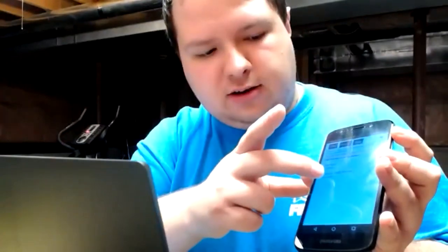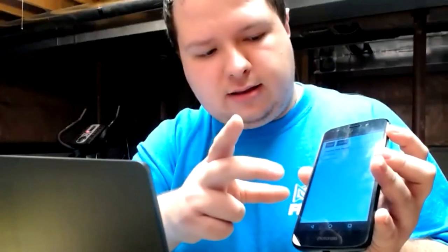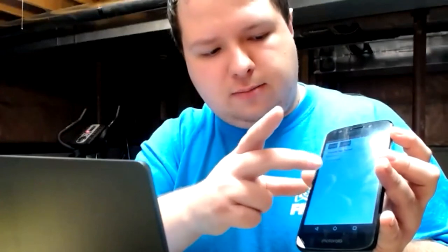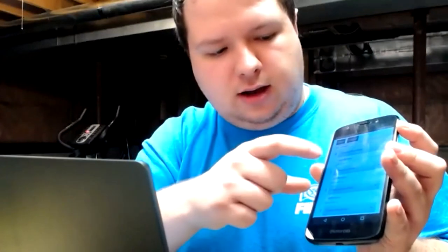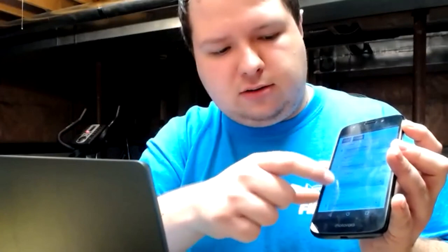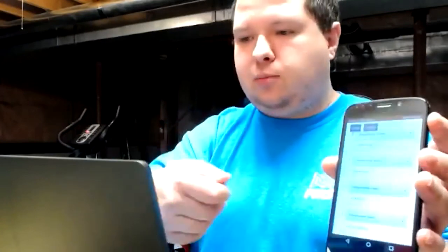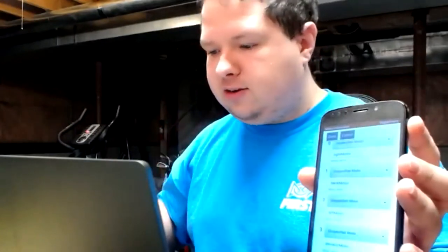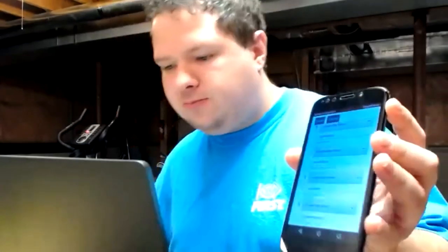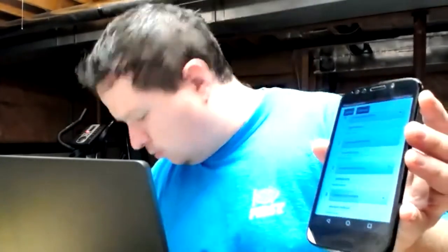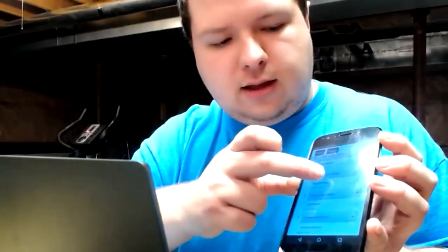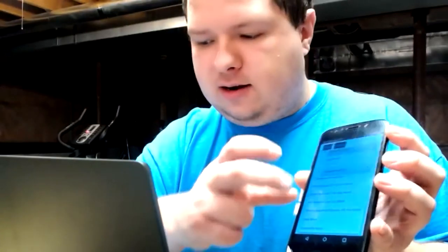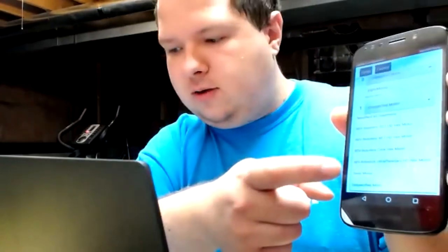You'll then find the Control Hub portal. Click on that. Click on the Control Hub. Then you want to click on Motors. And you'll see there's motor ports 0, 1, 2, 3. So depending on which port you plug your Tornado into on the Control Hub. So for example, if I plugged into port 1, I'd look at port 1. I'd click on the drop-down menu here, which allows you to choose which motor you want.